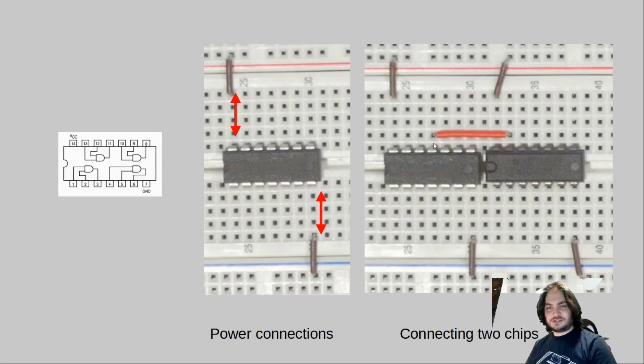When you want to connect two chips, you can just put a jumper in between their respective breadboard holes. Very often, internally, you're going to have packs of 4 logic gates, for instance, if they have 2 inputs and 1 output, and they'll go from one end to the other's input, input, output, input, input, output, and similar on the other side.